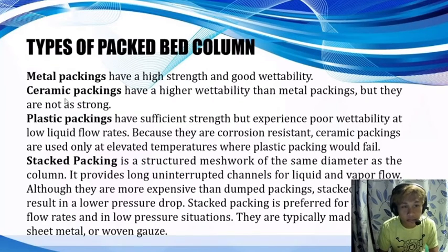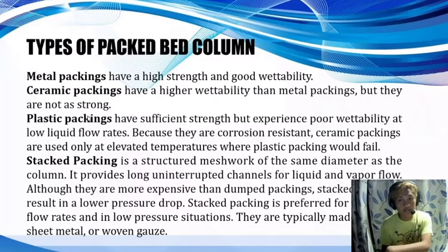These are the metal packings, ceramic packings, plastic packings, and stack packings. Metal packings have a high strength and good wettability. When we say wettability, it pertains to the ability of a liquid to maintain contact with a solid surface, and is controlled by a balance between the intermolecular interactions of adhesive type and cohesive type, which is important in distillation. So that's the definition of wettability.